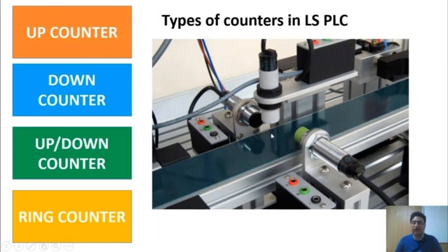Alternatively, we can logically OR 2 sensors together and then connect them to one of these counters. Consequently, when either of these 2 sensors is triggered, the connected counter will increment its value by 1 unit. So each and every one of these sensors can be connected to a dedicated counter within our program and perform the necessary counting operations for us.